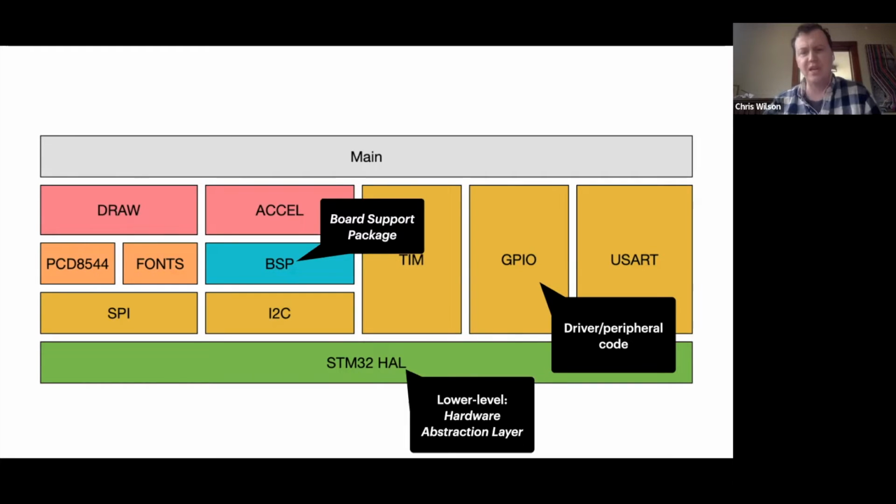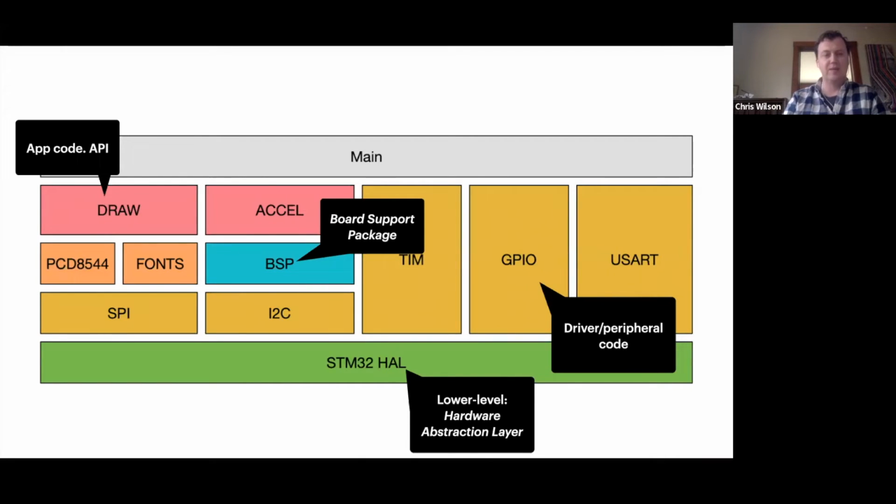And then BSP, you'll see that term come up a lot. It simply means board support package. The idea is that you are bundling up all of your code that is specific to the board that you're working with into one module, so that you could conceivably switch that out, and you write all of your higher level functions in terms of those board support functions. Yeah, and then I basically just had a big main, which was driving all of that.